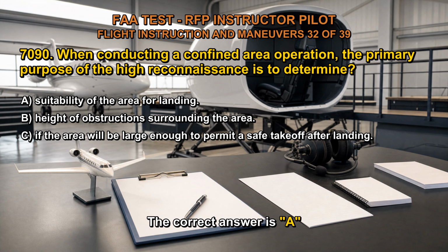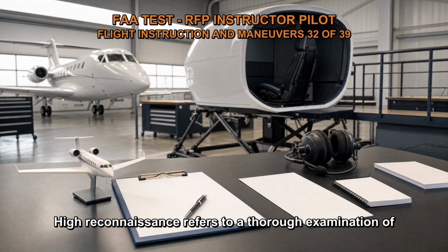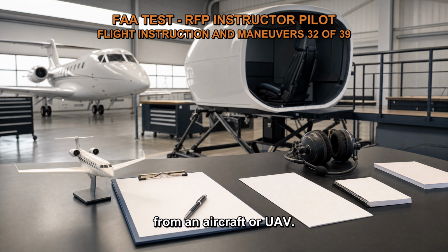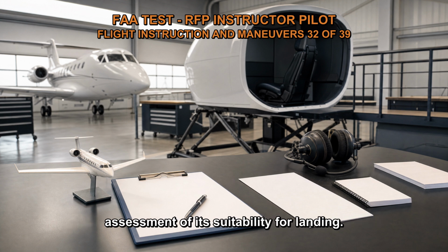The correct answer is A. When conducting a confined area operation, the pilot needs to assess the landing area to ensure it meets the necessary criteria for a safe landing. High reconnaissance refers to a thorough examination of the area from an elevated position, usually conducted from an aircraft or UAV. During high reconnaissance, the pilot gains an aerial perspective of the area, allowing for a comprehensive assessment of its